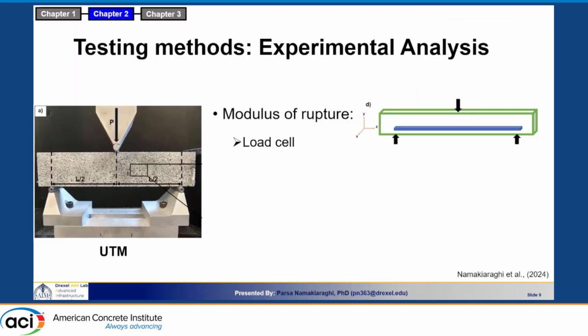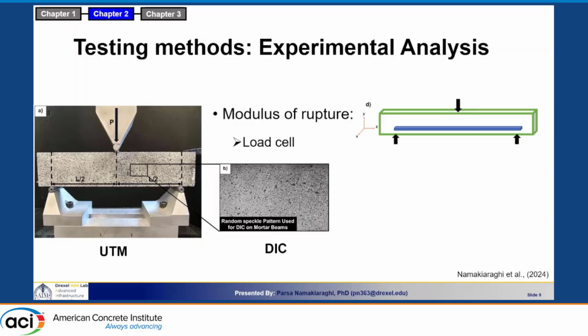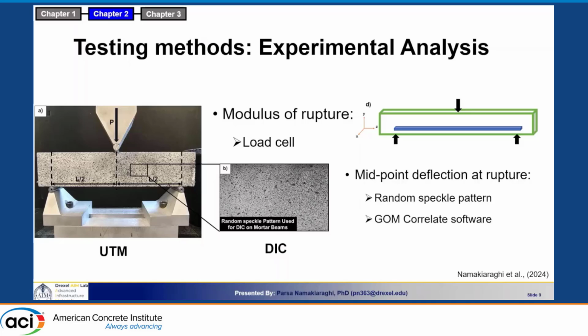For the preliminary tests on our simply reinforced longitudinal 3D printed reinforcement concrete, we used a simple 3-point bending accompanied by DIC in order to capture load displacement.